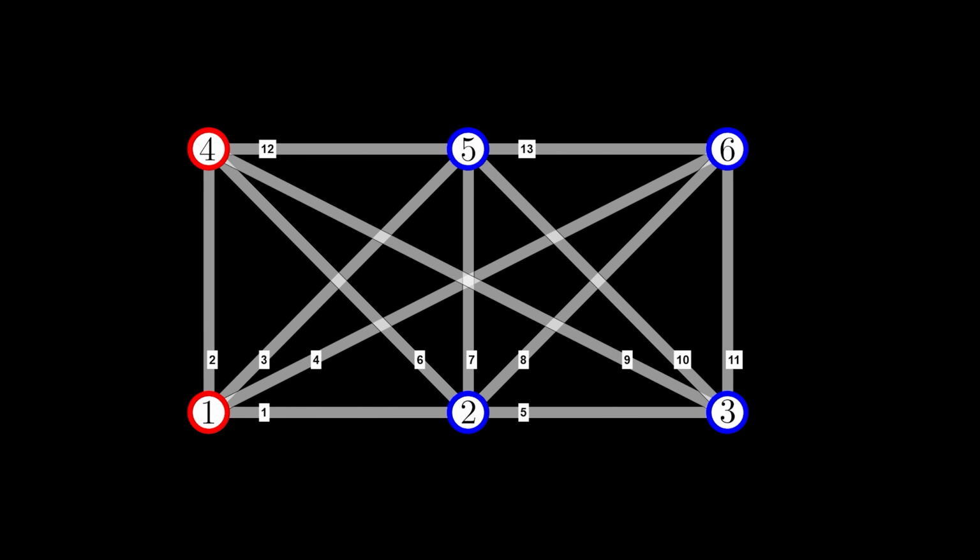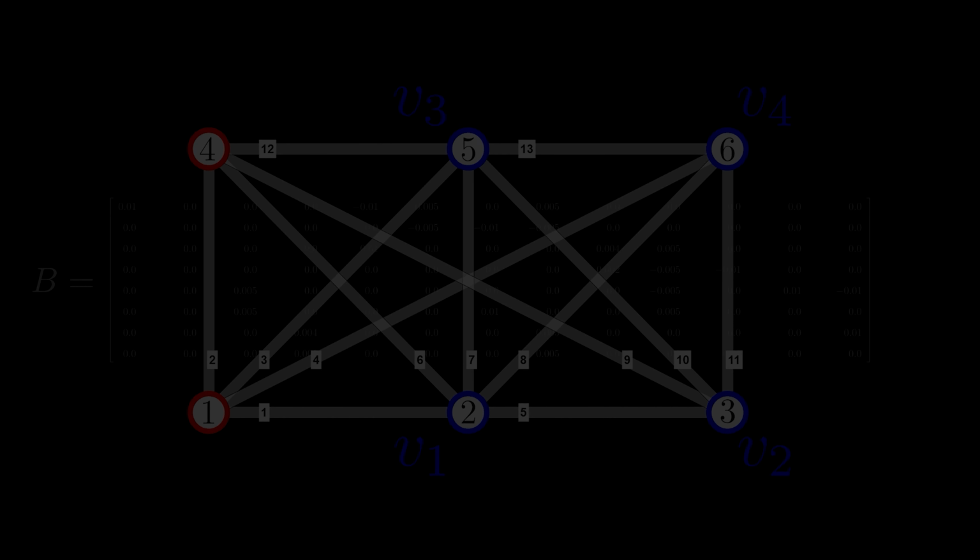We consider the following two-dimensional truss with nodes from 1 to 6. They will always be numbered from the left to the right, row by row. As you can see, we have 4 blue nodes in this truss, so we have 4 free nodes V1, V2, V3 and V4. I mentioned before that to calculate the optimal truss, we will have to calculate the vector BVW for every bar in the truss. The matrix B that contains all these vectors column by column looks like this.